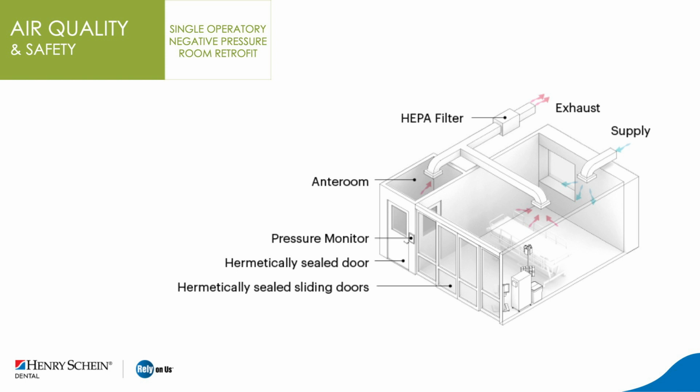And if we want to increase the fresh air supply, we're able to do that in real time, as long as we have these either mechanical or electronic controls on the air dampers in the air handling unit. And this allows us to exhaust or expel a higher ratio of the inside air, the recirculated air, and therefore rid the office of any airborne viral particles present.